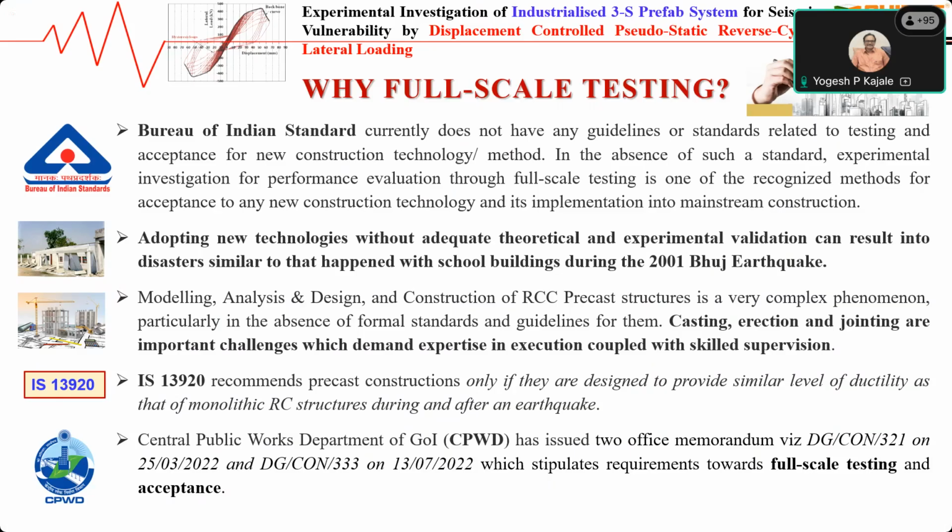IS 13920, which is specific about ductility, particularly performance during seismic events, recommends that precast construction can only be used if it is designed to provide a similar level of ductility as that of monolithic RC structure. This one-line statement allows use of precast construction systems in buildings, but only when it is established that they provide similar ductility as monolithic RC structure.